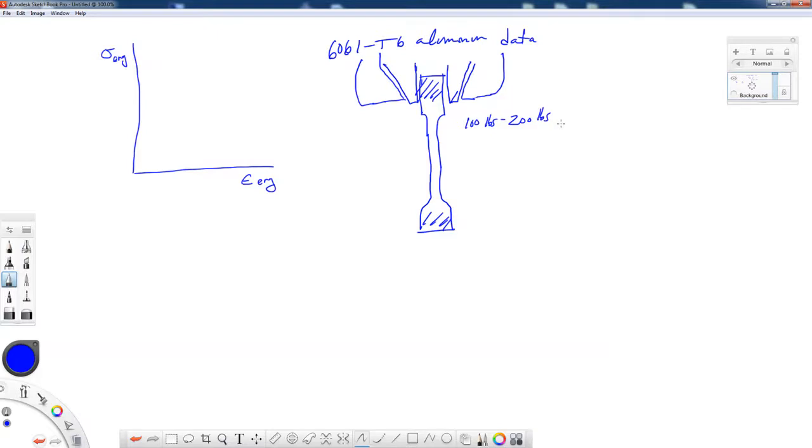Now, usually that is done before you apply the extensometer. So if you think about it, you're starting here at a stress level. That's your initial force, but you haven't measured any strain yet. You usually zero your extensometer after everything is all set up, and then you do your test.